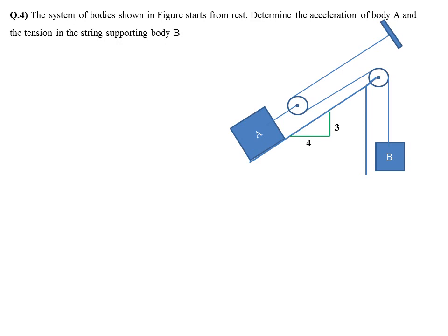Now, the inclination is given like 4 3. We already solved this kind of problem with the inclination given like 4 3. Now, the weights of A and B are given as 750 Newton and 500 Newton. So don't take it as mass, it is weight that is given. Okay, WA and WB are directly given. You can find out MA. How will you find out? WA divided by g, that is MA, and MB is WB divided by g.